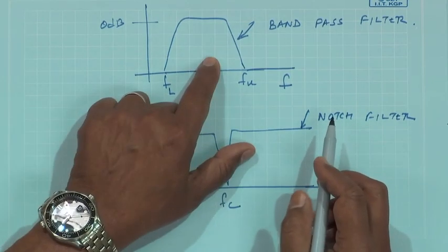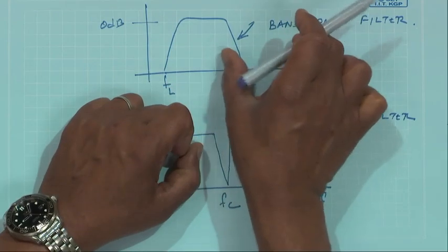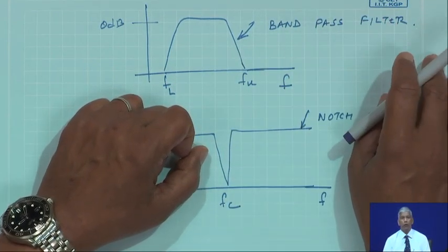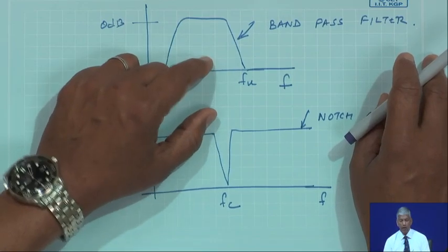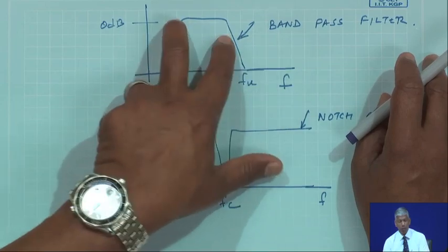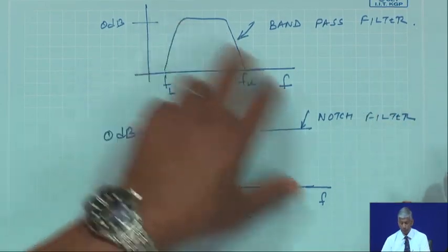I will talk about band pass filters a little later, because I can have a series of band pass filters, and to find out the frequency content in a signal, I could pass it through a series of band pass filters where the bandwidth is known to me. So, many times analog filter sets are used to find out the frequency content in a signal.